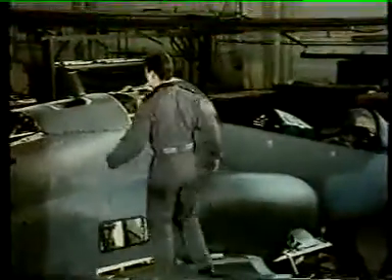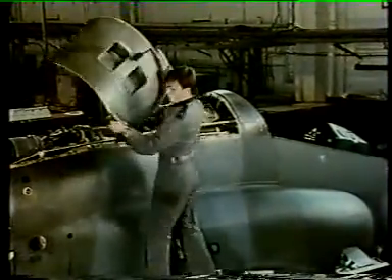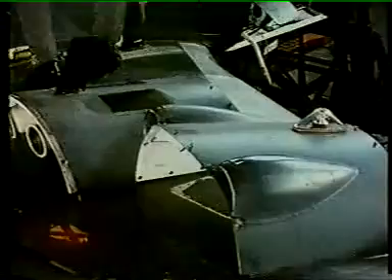Equipment or components being removed and scratching the surface. Failure to use protective matting on a wing surface. Snow removal being carried out harshly. Incorrect footwear being worn. The area around fasteners getting scratched. Careless stacking of panels. All trivial incidents on their own, but happening regularly over a period of months, the cumulative effect is serious. Corrosion is being offered a chance to take hold, a chance that's always accepted.